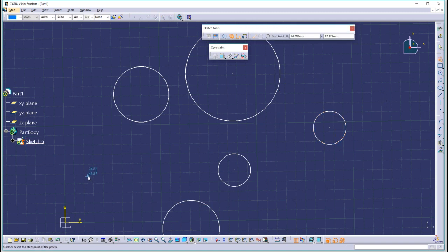So I'll start over here and I'll click, I'll pick up my vertical, and I'm having trouble here with my horizontal. See, it's snapping way over to those other things. So I'll hold my Shift key now to just temporarily turn off that detection. And I'll draw it like right here. I'll make it horizontal after the fact.